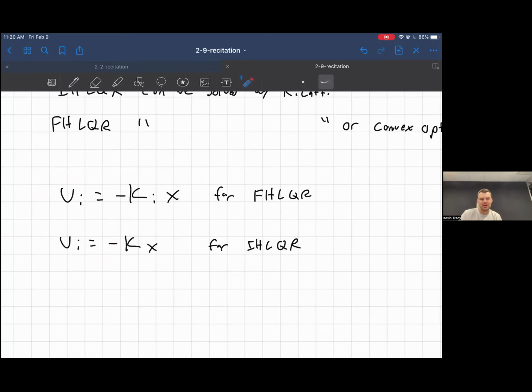I use that forever. So you imagine how appealing this is as a solution method for a control problem. If I was building a cruise control, I could just get a linear model of my system, say I want to optimize this thing forever, get just one matrix K, and then load this 2D matrix onto my robot itself and tell it to run. This is about as simple as it gets. And you would be amazed at the number of problems that are really complicated, high dimensional, all sorts of crazy stuff, and we can just solve trivially with infinite horizon LQR.